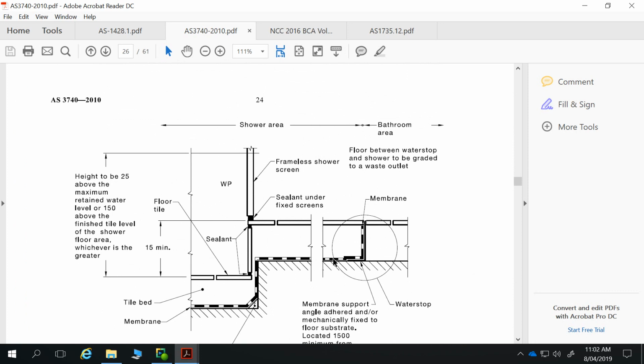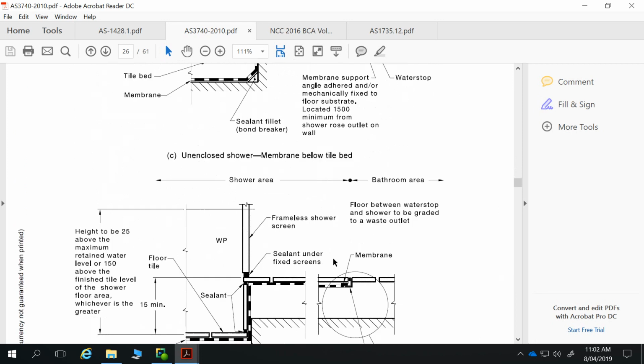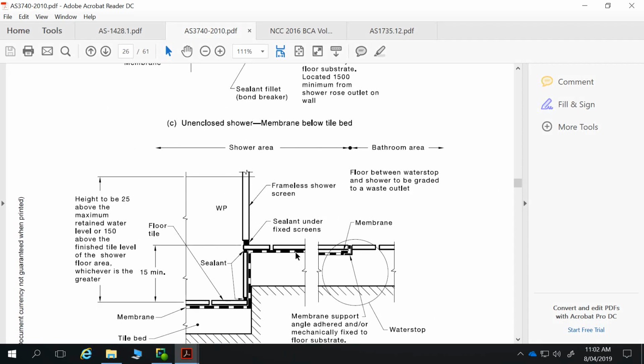The reason for that is that if we go putting our waterproofing membrane on top of our screed, then we end up fixing our tiles with our adhesive on the top of that waterproofing membrane. We have issues with compatibility of products, but then we also have damage of that waterproofing membrane whenever we go to renovate a bathroom.